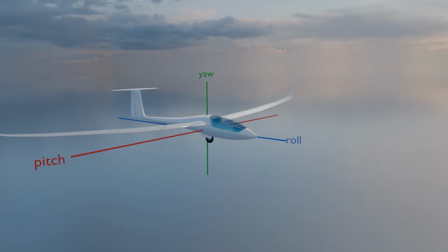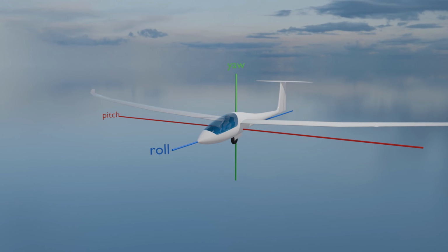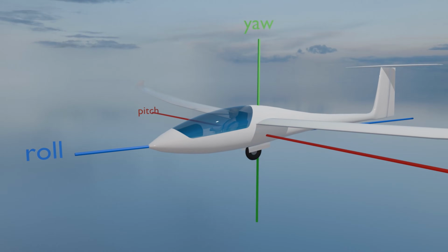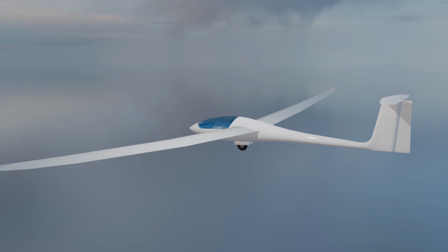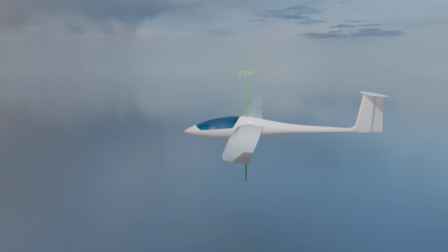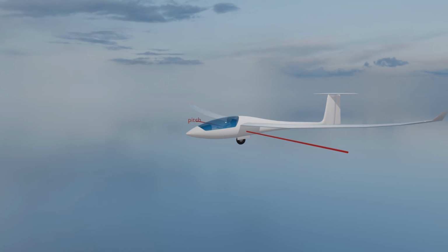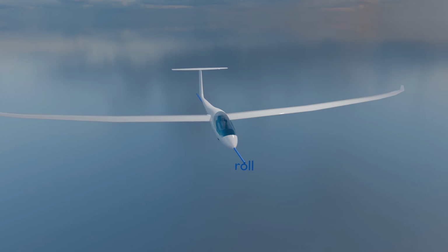Here's the deal. We rotate around 3 axes: yaw, pitch, and roll. That's all we've got, and it has to be enough. In aviation, these axes are tied to the airplane's structure. All 3 axes intersect at the aircraft's center of gravity. The vertical axis, yaw, runs from top to bottom. The lateral axis, pitch, spans wingtip to wingtip. And the longitudinal axis, roll, runs nose to tail.